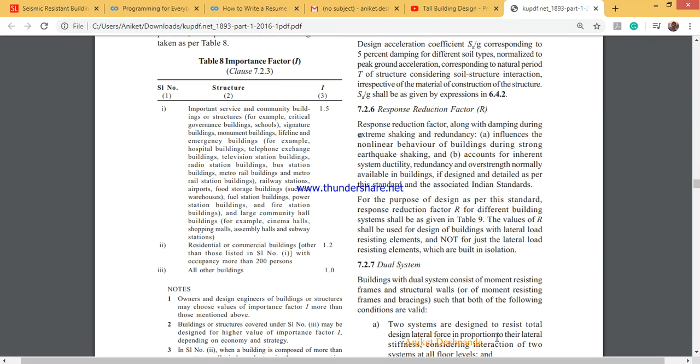So even if we consider one person for every 5 square meters, which is quite a huge space, we'll have to consider that is per floor, not 18, sorry, 180 persons per floor.